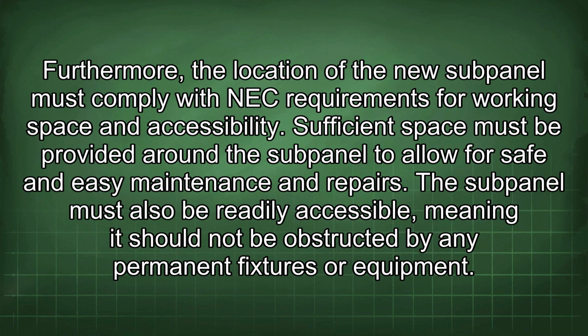Furthermore, the location of the new subpanel must comply with NEC requirements for working space and accessibility. Sufficient space must be provided around the subpanel to allow for safe and easy maintenance and repairs. The subpanel must also be readily accessible, meaning it should not be obstructed by any permanent fixtures or equipment.